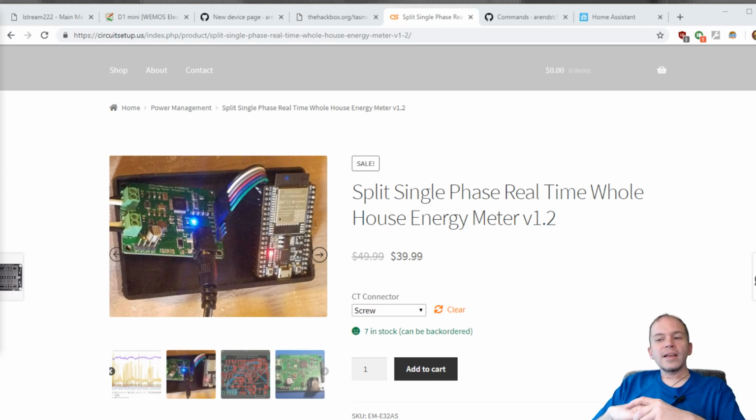Yes, non-contact voltage testers. Yep. I didn't have one for a while. I even mentioned it in that Moe's 3-way video. The reason why I say this: never trust the electrician that was there before you. Because you think, oh look, I cut this off and it cuts these lights off, and hey, I did cut the breaker off.